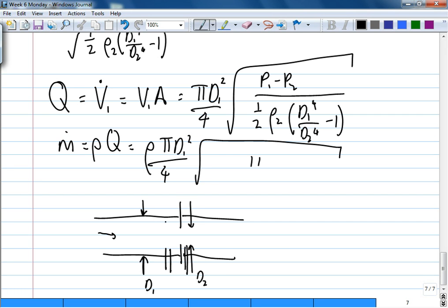So the flow would squeeze into this hole, and then further out, it will expand out later. So you all know what an orifice plate is, isn't it? It's just the two flanges of the pipe. You put a plate in between, and the plate has a smaller diameter, D2. So this is an alternate arrangement.